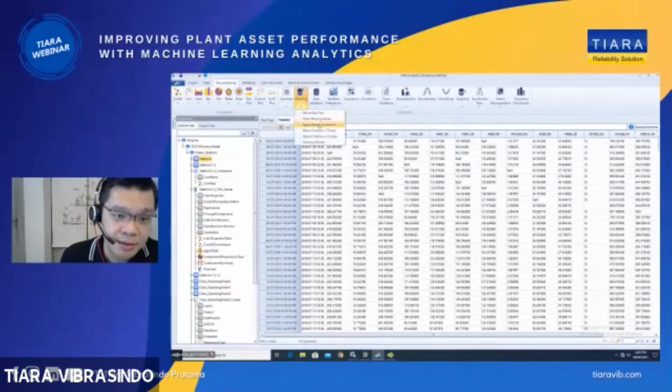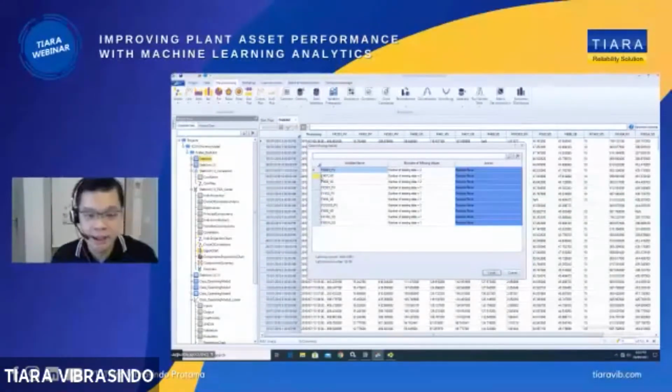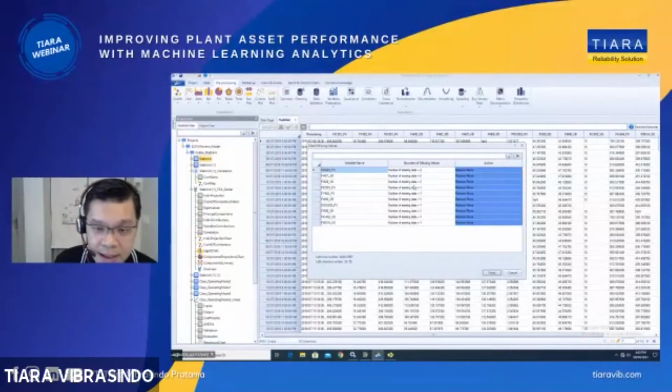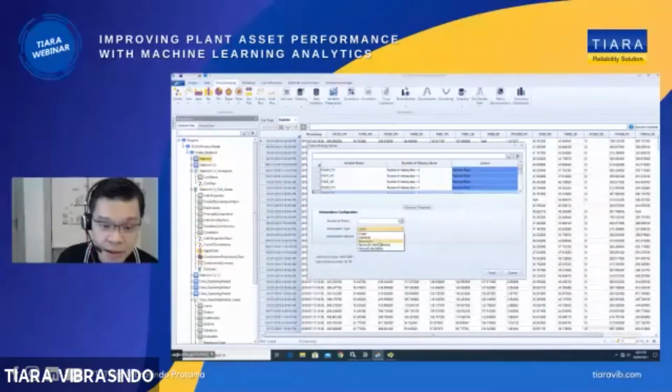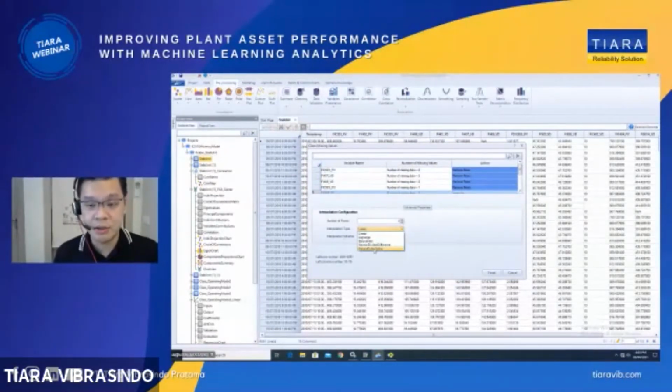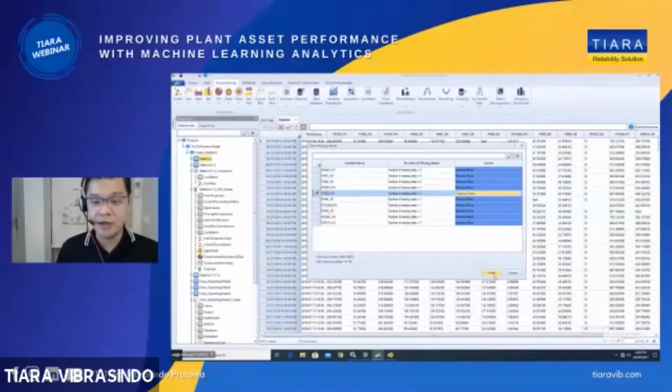Just for example, let's say I want to clean it up. I can just ask it to show me what the missing values are. The software searches through this huge amount of data for any missing sensor readings. If there is a missing sensor reading, what would you like to do? You may want to do interpolation for those missing data. If you do interpolation, which algorithm do you want to use to replace those data with a meaningful value? The software comes with all of these, or you can do an impute to replace them with certain values. For simplicity in this demo, I just remove this data. If you have a lot of data, you can just remove it.